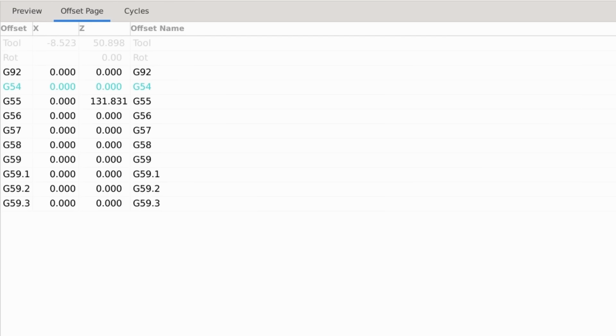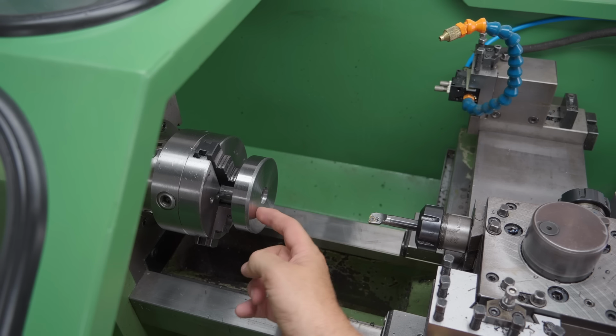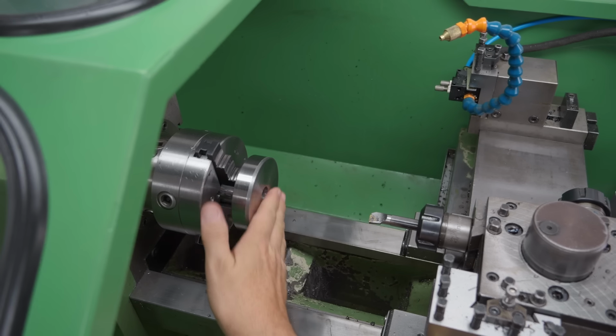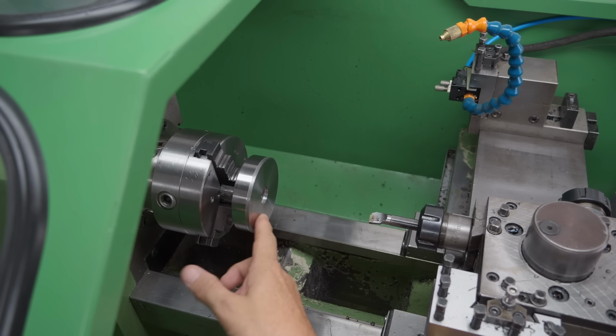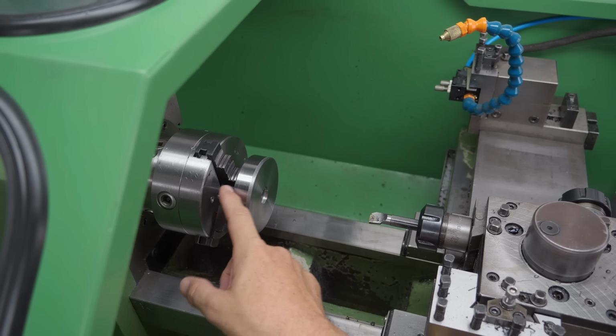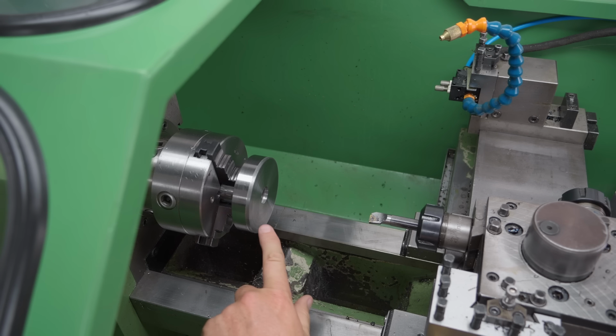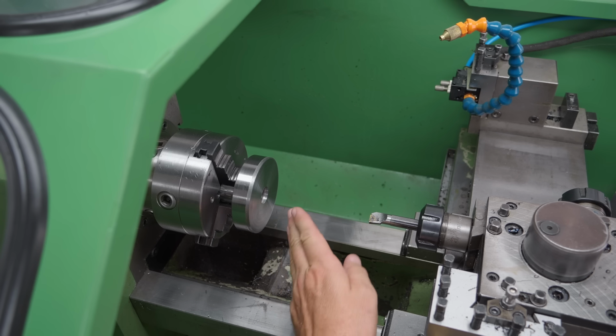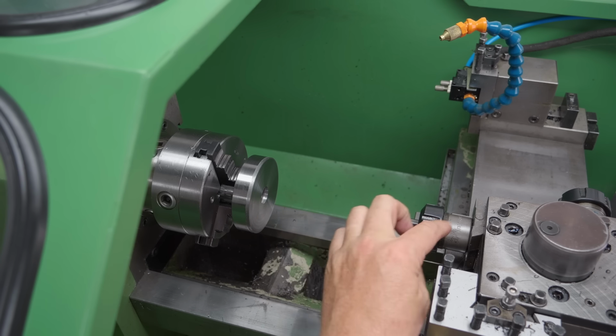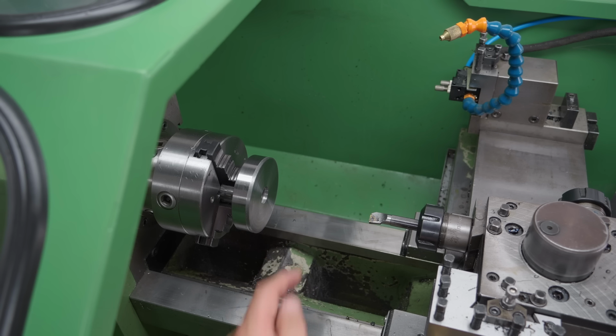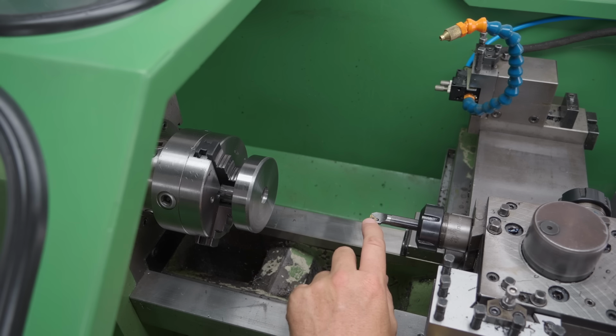This also means on a lathe like this, I shouldn't use the workpiece offset in X. I can use it in Z to set whatever is the end point of the piece of work at Z0 so that all cutting moves are negative. That's quite typical for me, but I shouldn't be offsetting from the center line at all with the work because it's a lathe. Any offset from the center line should only be done at the tool level.